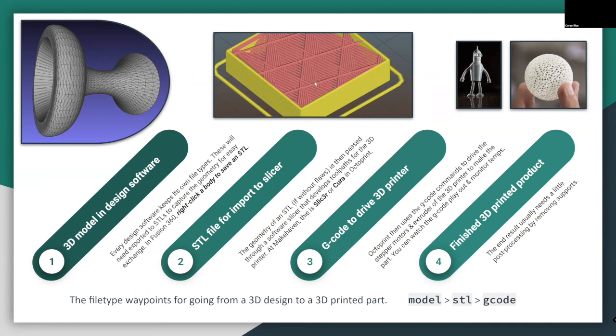And once it's got that, then the G-code is what the 3D printer actually uses as instructions for how to make it. G-code is common across all of our machines. So the laser cutter and the vinyl cutter and the CNC, they all use G-code, but probably 3D printing is where I learned about G-code the first, right? That it's just a series of instructions for motion from a set of stepper motors. And it turns out the 3D printers are very nice and very vocal about that's what they've got, and that's how they're moving it around.